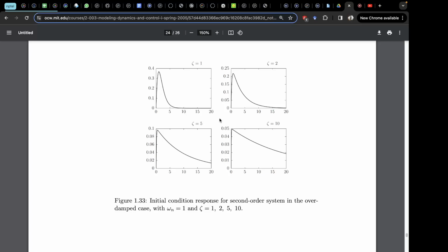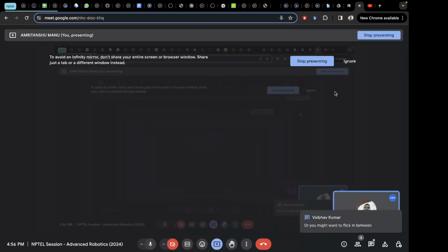You might want to move around some obstacles, or go through some point. So you want more flexibility in your path. For adding more flexibility, you have to stitch in more polynomials. The higher the number of polynomials, the more shapes your path can take.